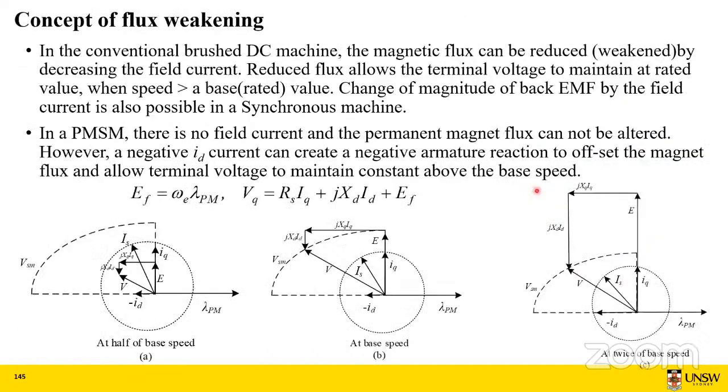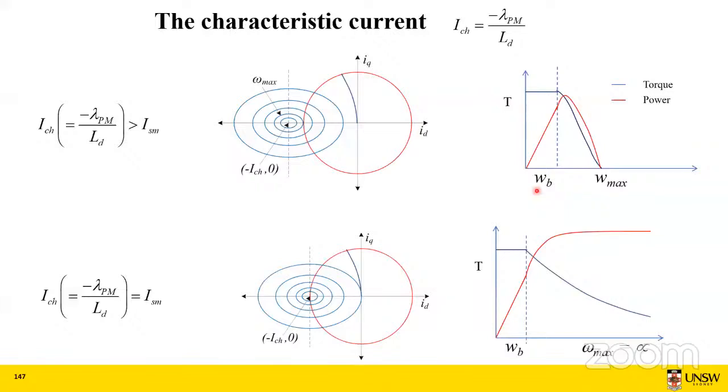Whether the center of the ellipse sits outside of the current limit circle or at the boundary of the current limit can actually be decided during the machine design, because you can design in such a way. So this could sometimes be an objective in machine design, especially in optimization, which we'll discuss in tomorrow's lecture.